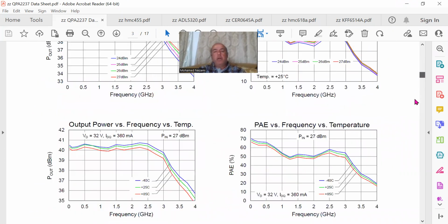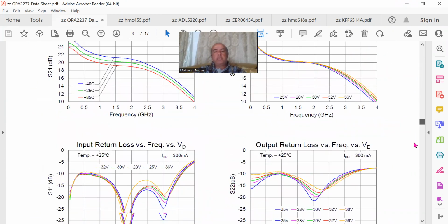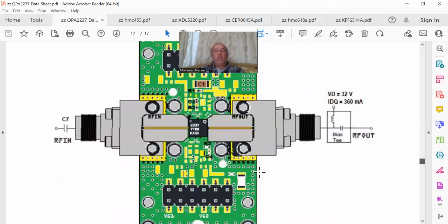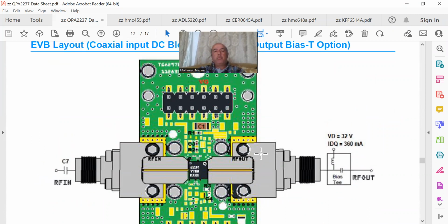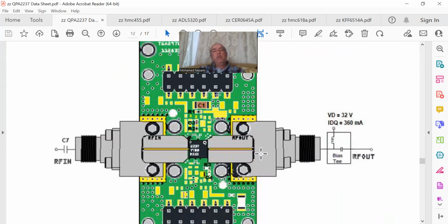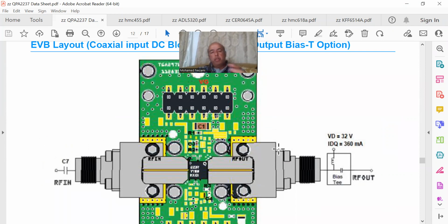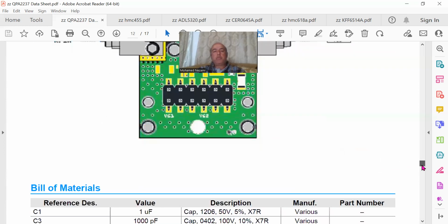And in the past, what I did before I used this device is I purchased this board from Qorvo and experimented with this device up to the point where you're comfortable with it, because every time you blow one of these up, that's $50, $60. So it's preferable that you first accumulate experience based on using their evaluation board that comes in. It's better that way, okay?